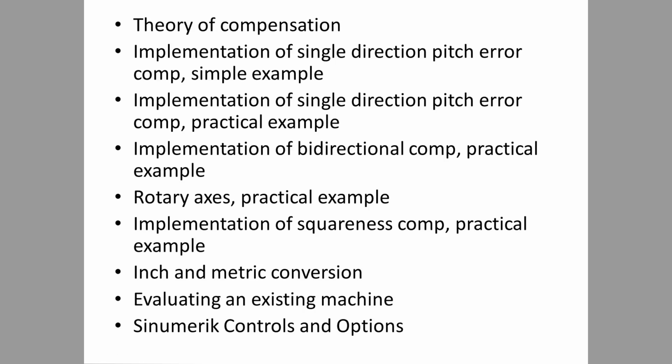So we're going to start with the theory of how comp works. Then we're going to take a machine tool, which has never been comped, apply comp to it for the first time to show how data in the different registers is handled, how we access the data, how the data is stored, how the control interprets it, and how we can modify it. We'll do this for linear axes, and we'll do it for rotary axes.